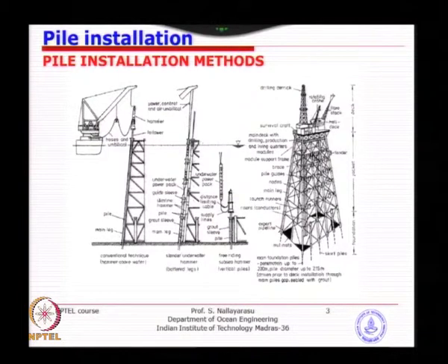Once the pile goes inside the jacket, it is invisible. So, nobody is going to go inside and take the pile backwards. So, you need to calculate the pile length in such a way that you estimate the penetration into the soil as x meters, you know the length of the jacket is y meters, plus you need to see the pile a little bit longer, say 5 meters, 10 meters, and this is what normally happens.